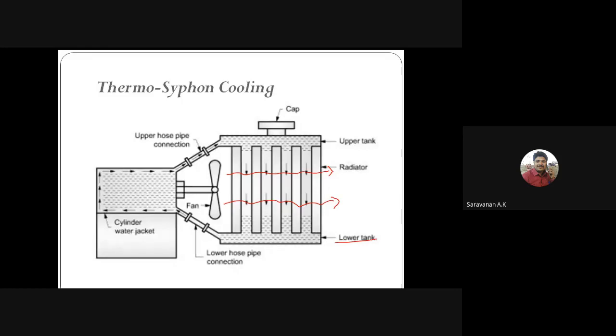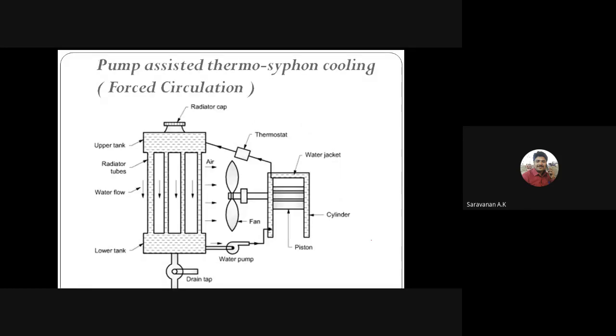Thermosiphon cooling system, right? In some cases we require some pressurized fluid in the engine block. So at that time we have to add some elements, mainly the water pump and the thermostat. So here it is also the same thermosiphon cooling system, but the water supply will be in a forced manner.